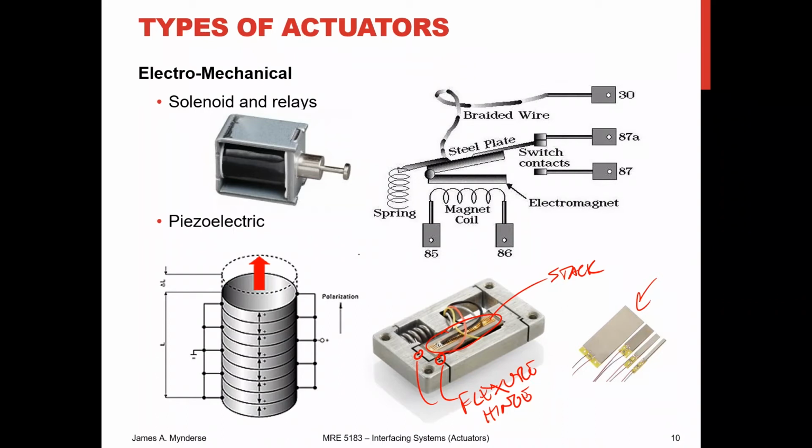Again, you have to be careful with piezoelectric material because one of the things they also can do is generate heat. And I saw a great example of this with a plate like this, where a student was looking to control the curvature of a helicopter blade by actuating the piezoelectric material. And when they did that, they unfortunately were vibrating it very quickly and not thinking about the heat, and it was sitting flat on a table, and it went into a runaway heating and burst into flames. So you got to be a little careful about runaway heating on these things.